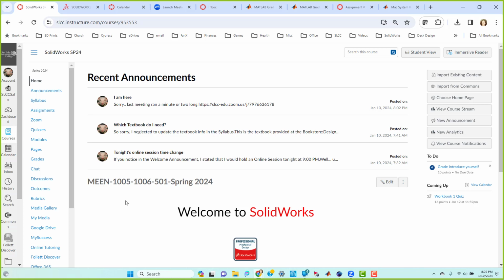I even have a program for MATLAB that, well, we determined it wasn't worth it, but it's EMS, electromagnetic studies, where I can simulate a magnetic circuit and find how the magnetic flux will flow through parts and this, that, and the other. But I did a study on our 6-inch tool based off of the geometries and materials of our tool and put it into a pipe and got results, and they were nowhere near what our tool was reading in the pipe. So we lost all confidence in the output of that thing. But it's kind of cool. It makes nice, pretty pictures.